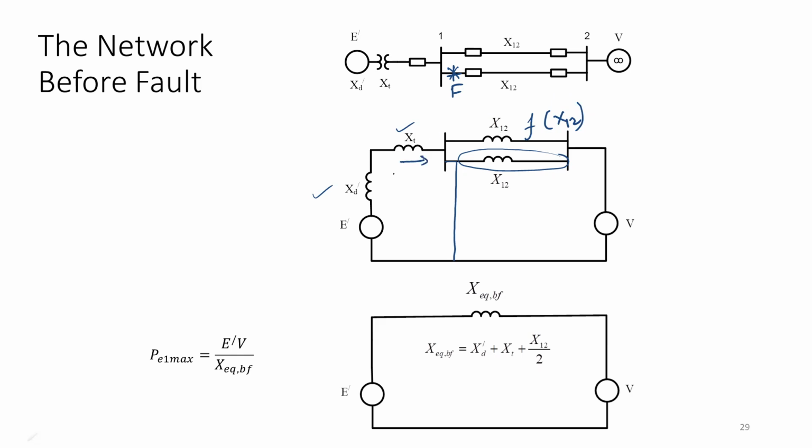First of all, current I1 will come over here. Now it has 2 paths. Say this is I2 and this is another path, I3. According to the current division rule, I can write that I1 is equal to I2 plus I3. Is it okay up to this? Applying KCL, can I write this thing? All of you agree? Okay.